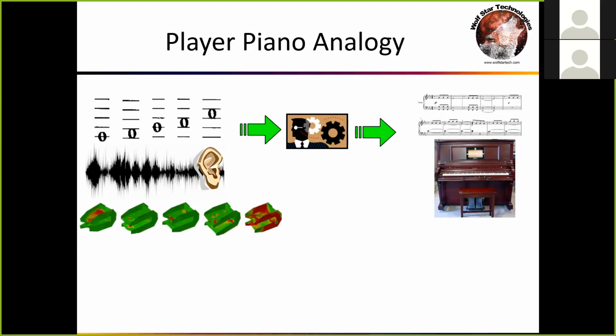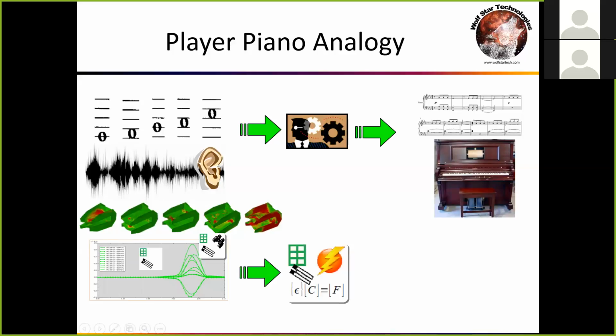With true load, we take our component part and put unit load cases on it. Those unit load cases create strain fields on the part. Now that we've got strain fields on the part, the pretest software is going to look at those strain fields and try to place strain gauges to uniquely identify each strain field. Then we place the strain gauges on physical parts, collect the strain data from the part, and bring those strain measurements into post-test, where we take the strain measurements times the correlation matrix to generate the loads, and we get these time histories of loads.